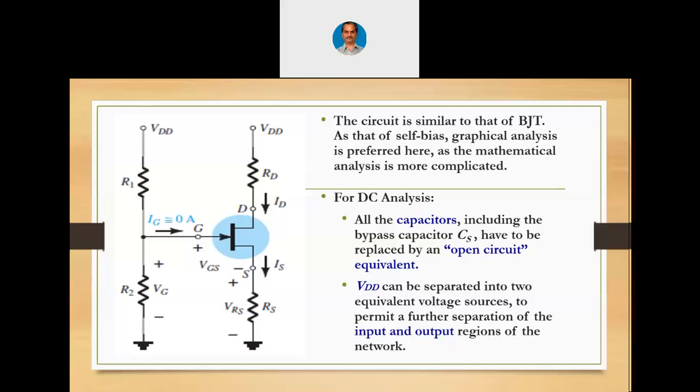It is not gate to source voltage. Please remember, it is not VGS. It is VGG or we can say it is VG itself. Gate voltage with respect to ground. Later on we will find out VGS by applying KVL to the output side also.